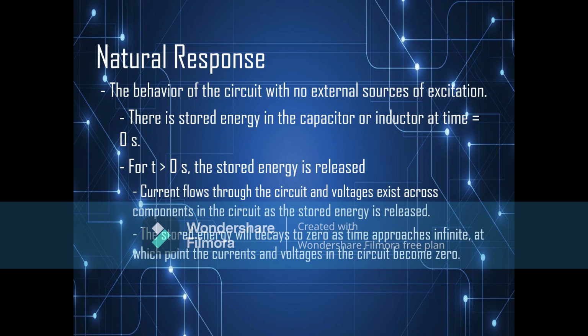Natural response: the behavior of the circuit with no external sources of excitation. There is stored energy in the capacitor or inductor at time t equals 0. For t greater than 0, the stored energy is released.